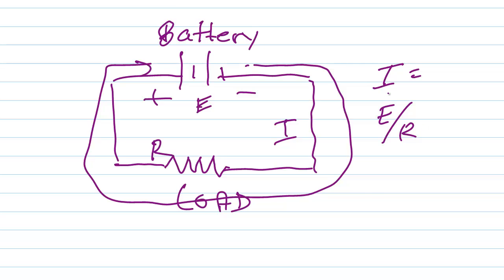The current in amperes equals the voltage in volts divided by the resistance in ohms. So if you reduce the resistance, you increase the current if you keep the voltage constant. Now, when you talk about where you're going to ground this circuit, you don't necessarily need to ground a DC circuit like this at all, particularly if it's a low voltage circuit. But if it's a high voltage circuit, greater than about 12 volts, any voltage that poses the risk of an electric shock, any risk, you're going to want to ground that circuit.